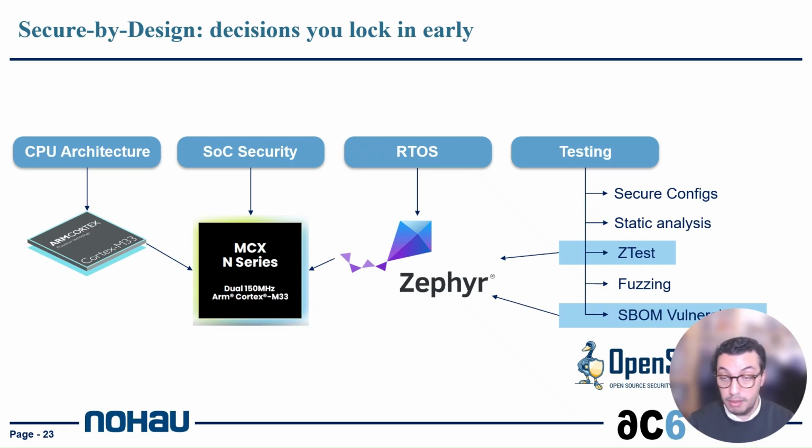Because Zephyr produces an SBOM in SPDX or CycloneDX format, we can track all third-party components and libraries included in the firmware. You can also check the OpenSSF ecosystem. They have a lot of tools that are all oriented toward security. We can check the CVEs associated with the dependencies. We can do a lot of things in testing, so I'll let you check the OpenSSF example.